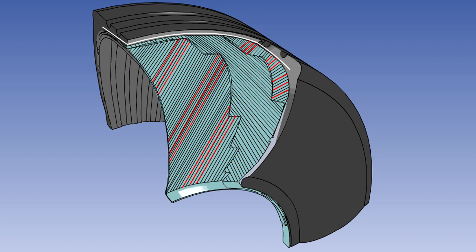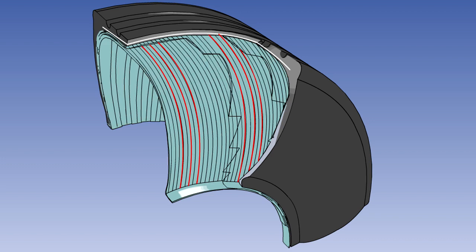During construction of the tyre, the plies are fitted in pairs and set out so that the cords of adjacent plies are at 90 degrees to one another in the case of bias or cross-ply tyres, and from bead to bead at approximately 90 degrees to the centre line of the tyre in radial tyres.